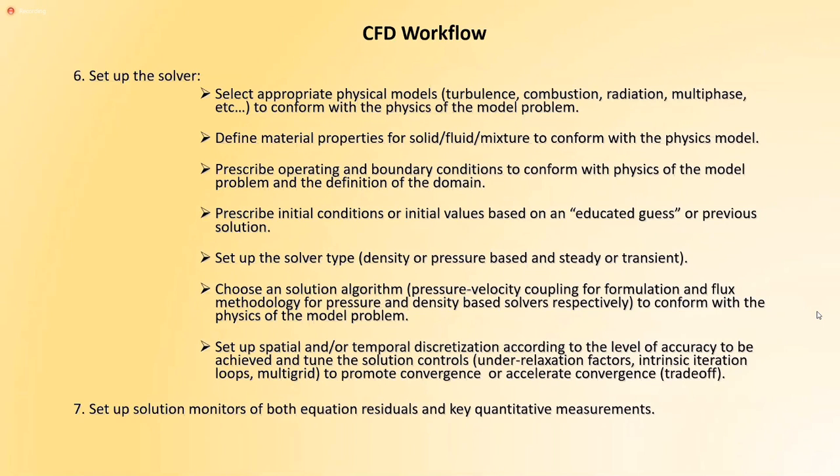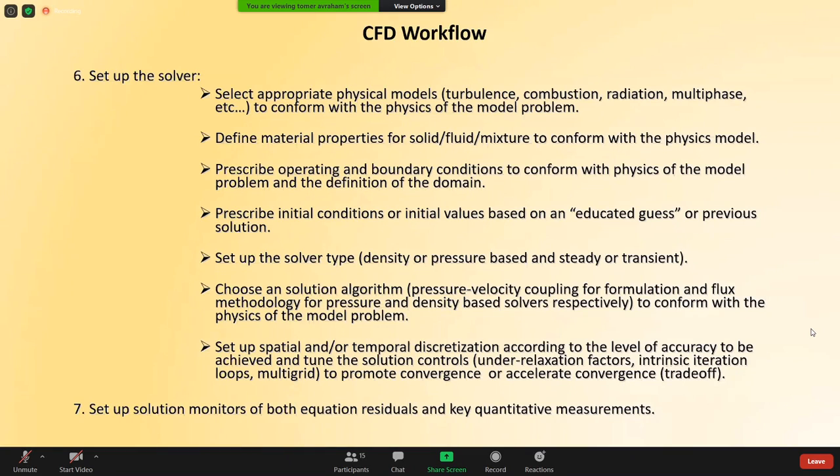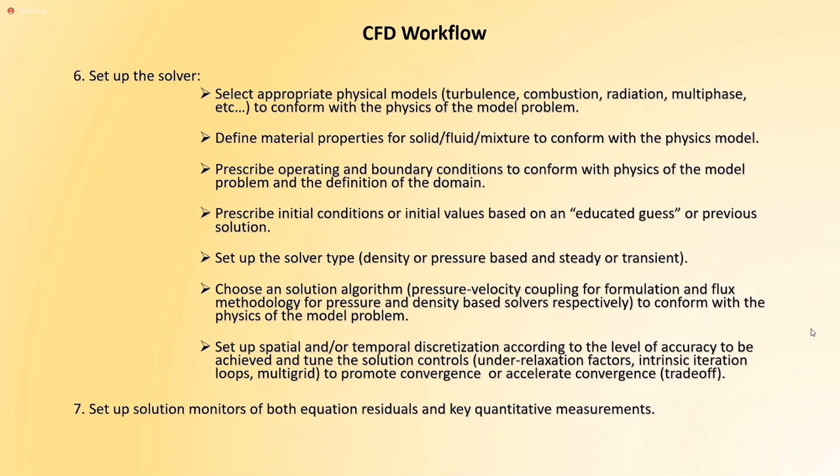You might think, I define the mass flow rate or a volume flow rate at the inlet, or, I know the area, so I can define a velocity inlet the same way. It is not the same. Usually most software prefers conditions like velocity inlet and pressure outlet. It's important because they transform to velocity anyway. So take this into account.